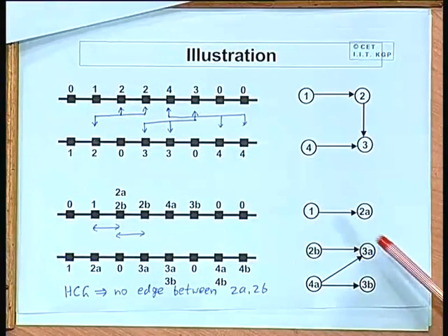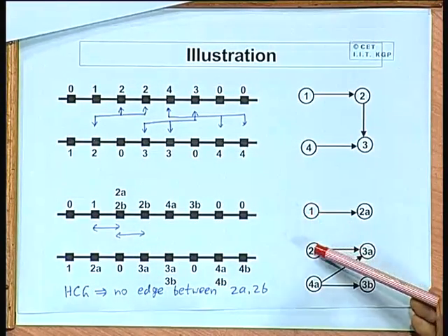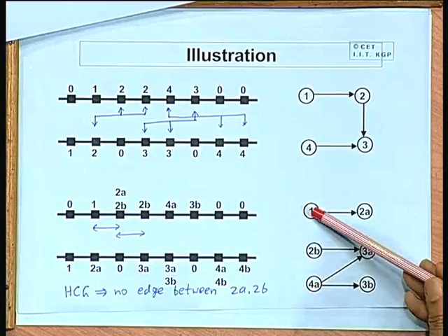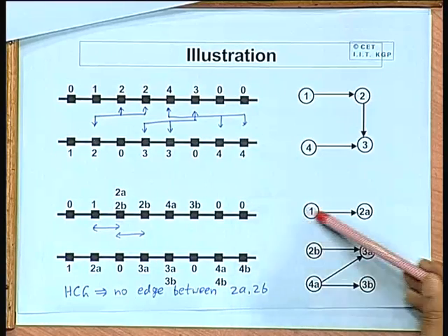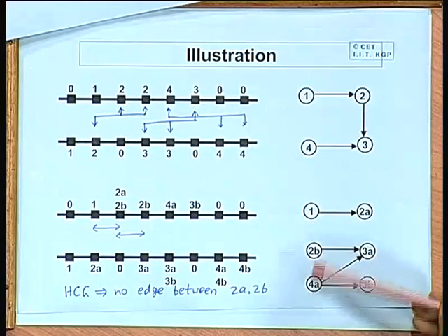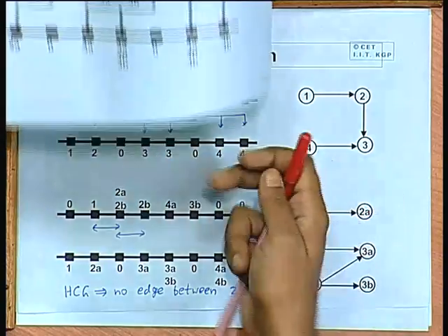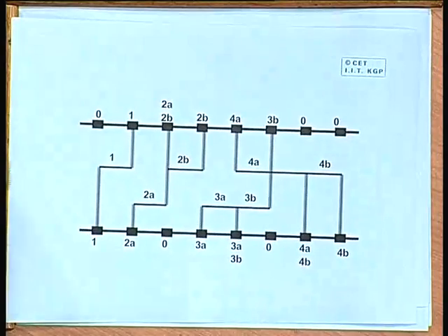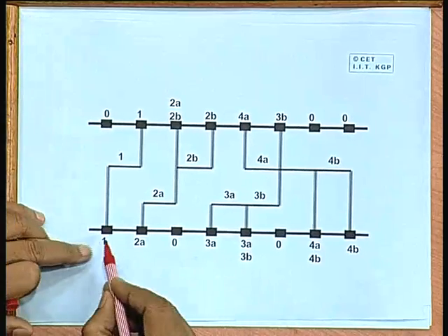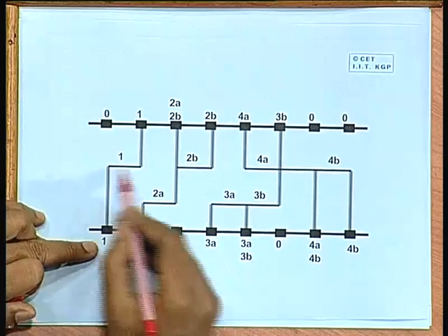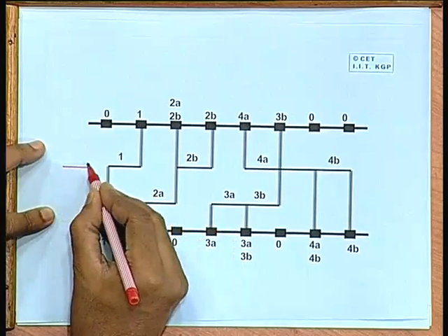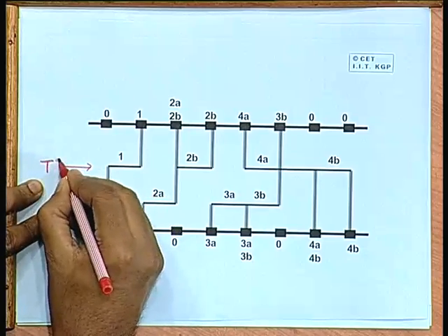Look at the constraint graph, 1, 2b and 4a are the ones which do not have any incoming edges. But once you finish 1, you can also start with 2a. So, here from the left edge net 1 comes first. So, you assign net 1 to first track, this is your track 1.